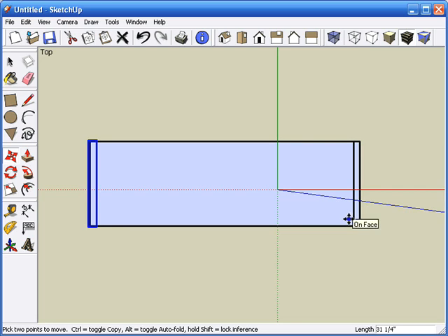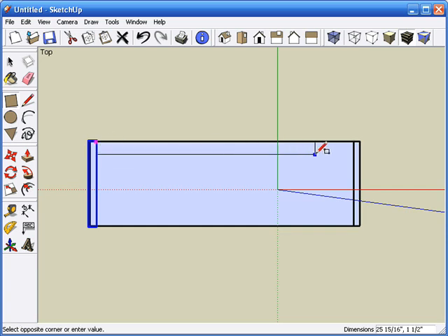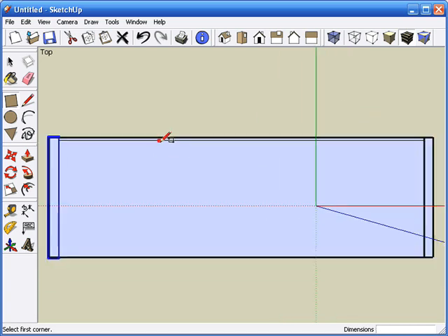Now let's do the interior sides. I'll click on that rectangle tool again. And actually, before we can do the interior sides, we have to do the back. So we'll draw a back on this bookcase. We'll draw it across here, and we can see it's 30.5 inches. And according to the dimension box, it's 1 1/8, but we're actually going to make it 30.5 by 1/4. There we go. See the dimension showing up in the dimension box, and I pressed enter, and now it's sized itself to 30.5 by 1/4 of an inch.